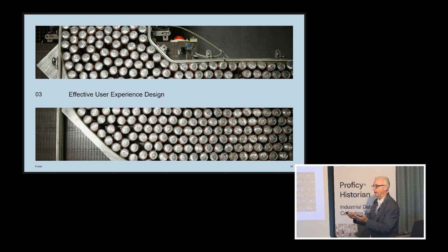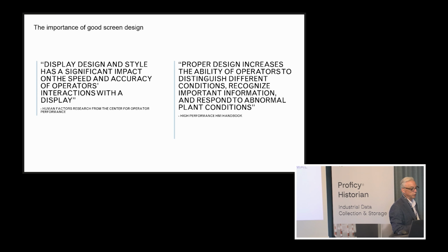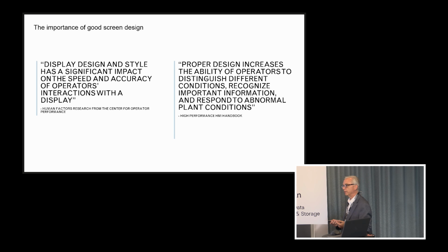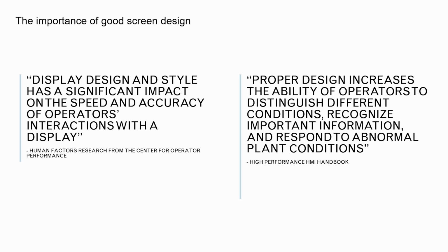We make a one-time investment in deploying a SCADA system. We think we knew 10 years ago or 20 years ago what was the right way to create screens. We created a visual representation that looked like the plant so that they immediately understood the context. People are smarter than that, right? They don't need a photorealistic HMI screen of the plant or of the piece of equipment.